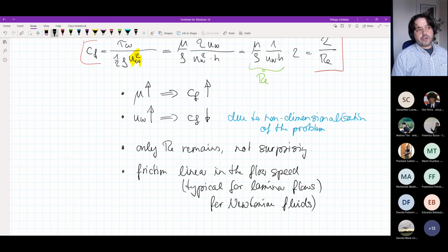But as soon as you go into, say, the food industry, where you have to deal with mayonnaise and toothpaste, the typical examples, then this is not good anymore. Blood flow, as blood is not Newtonian. But this really depends on the type of fluid: shear thinning, shear thickening, and so on. I guess I didn't answer very much, apart from saying that this is only valid for Newtonian fluids. I hope that's okay.